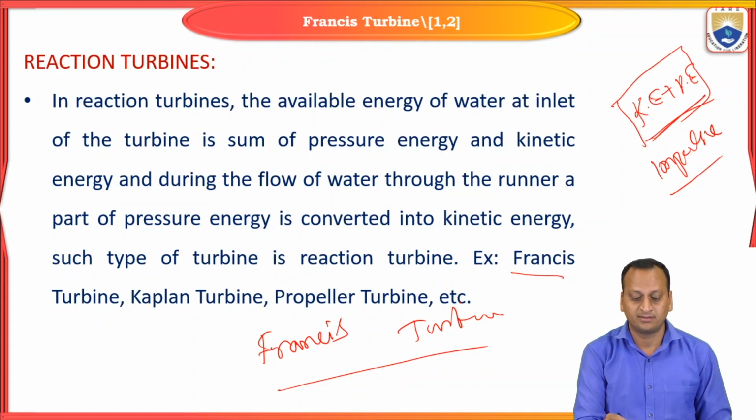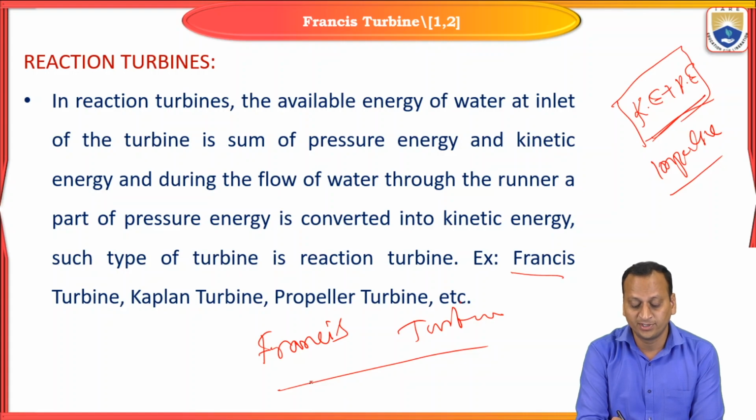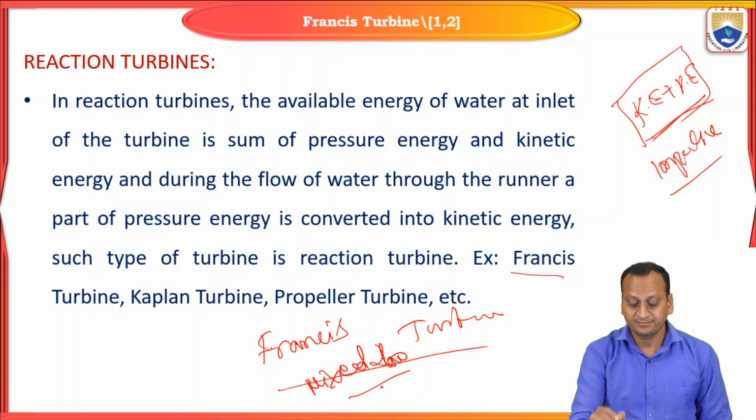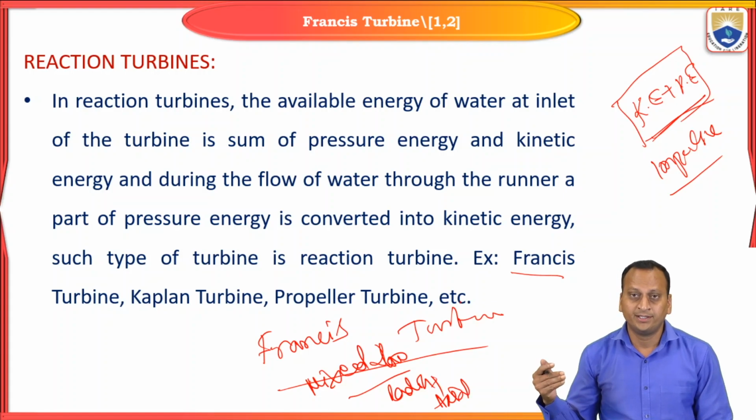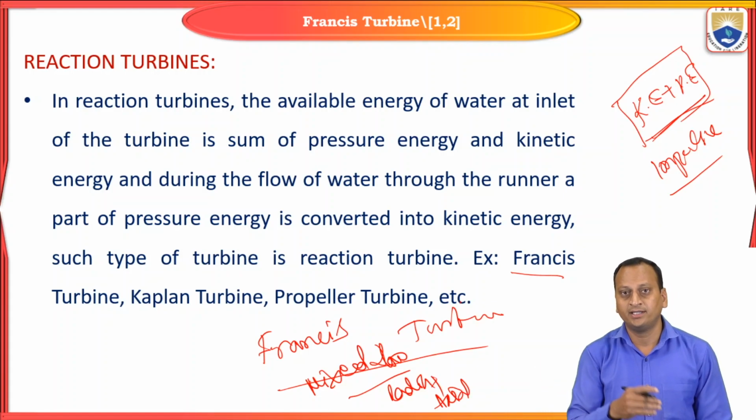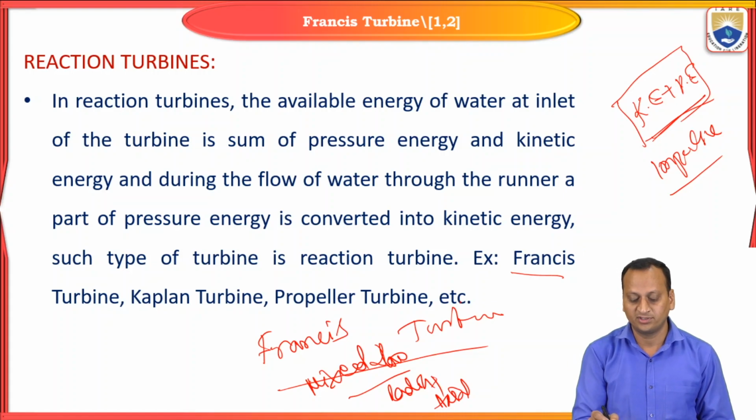In the case of the Francis turbine, the type of flow is mixed flow, due to both radial and axial flow being available. It enters the rotor in the radial direction and leaves axially. Therefore, this comes under a mixed flow turbine.